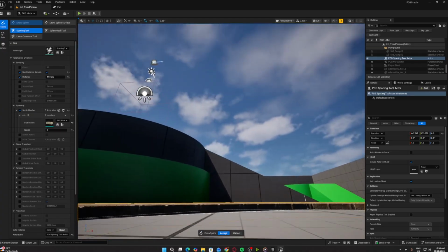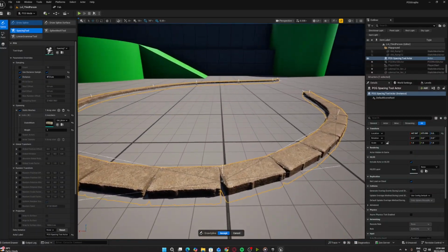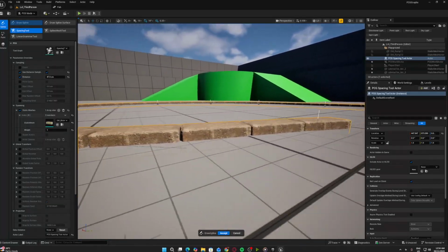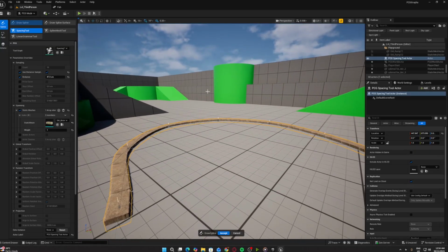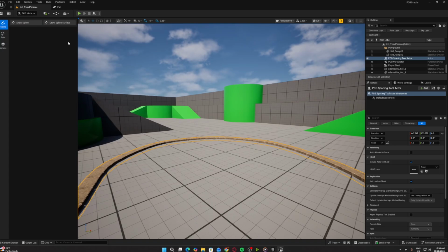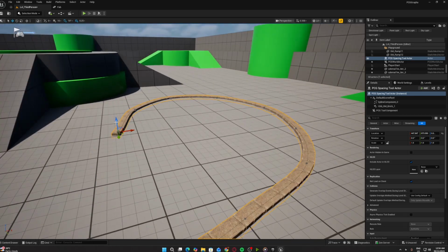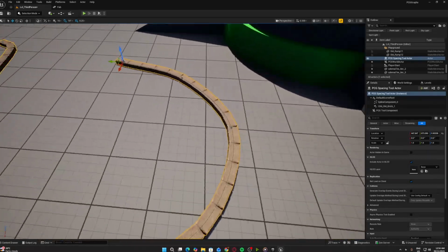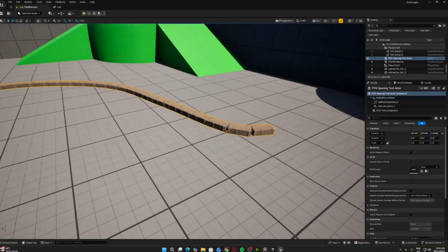When you put in 47, it's going to follow exactly the length of the brick mesh, the static mesh that you've created. So if I accept now, this becomes a selection that I can control and bring up here. So this is the path that we created with the spline tool in Unreal Engine 5.7.